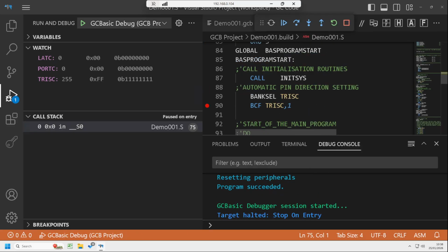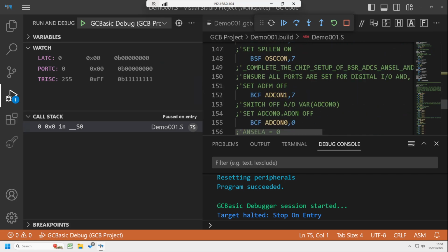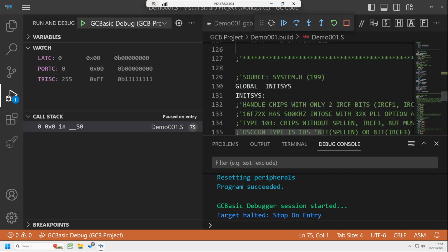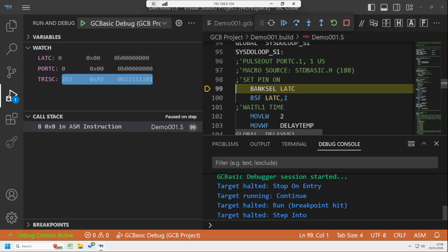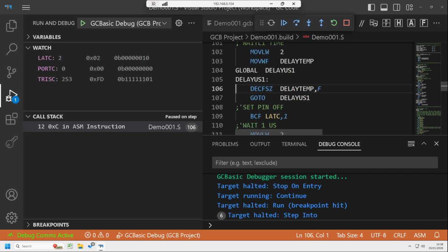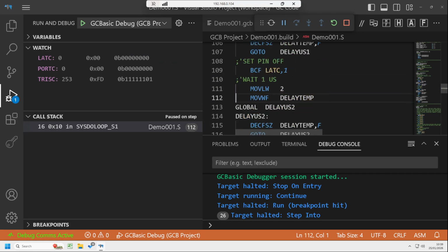And in here we can see that we've got essentially the same code, but trust me, the initialization is totally different. The frequency setup, etc., is different. And so I can run the code by pressing function key F5, and we'll see the variable LATC change as I increment through. The 0 and 1 in the top left there is turning on and off.